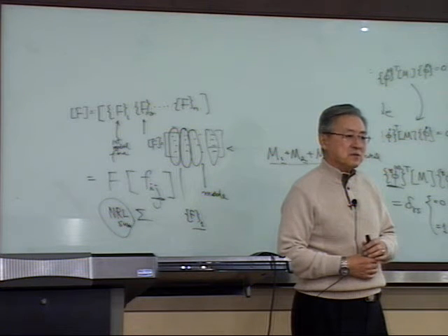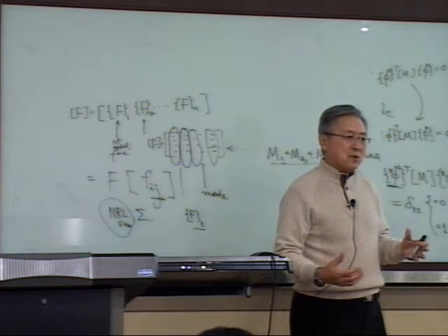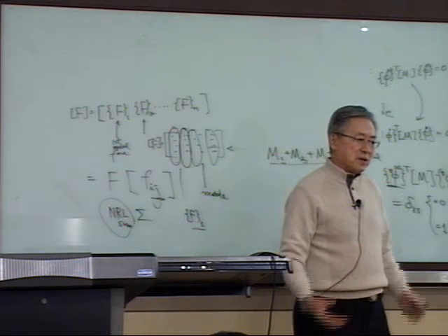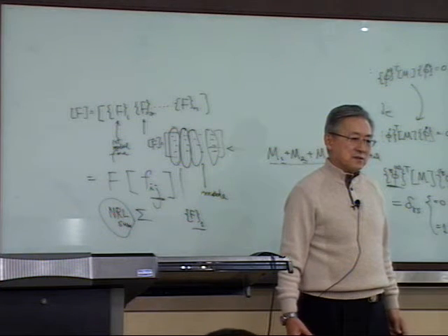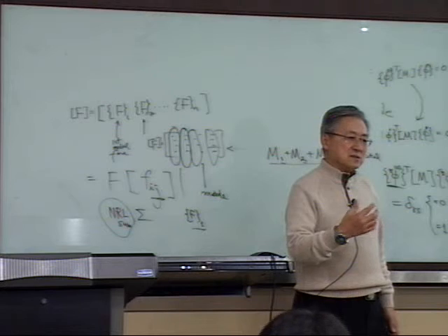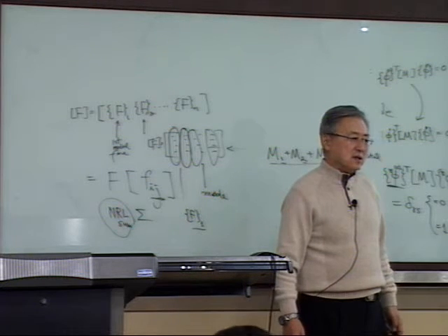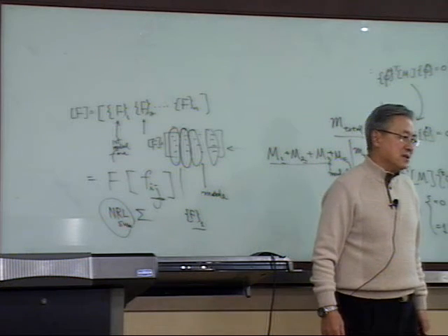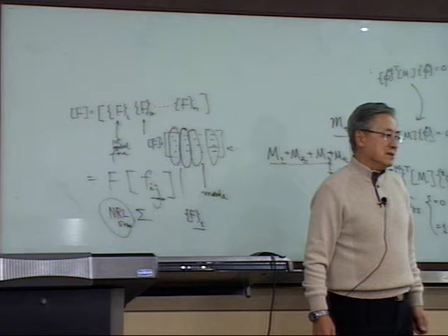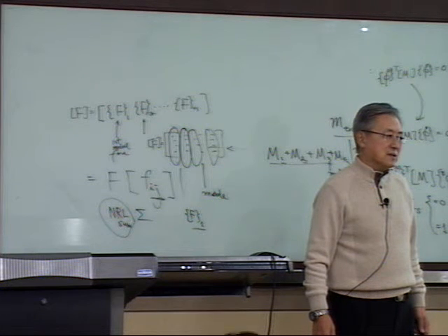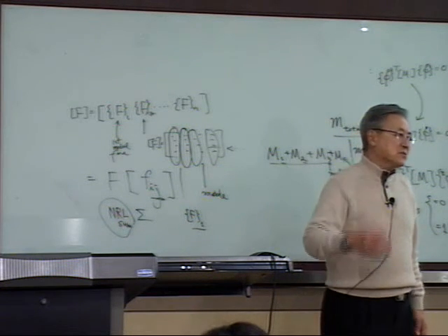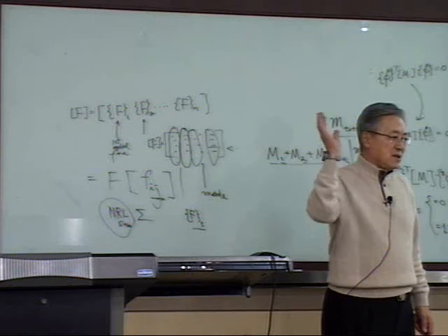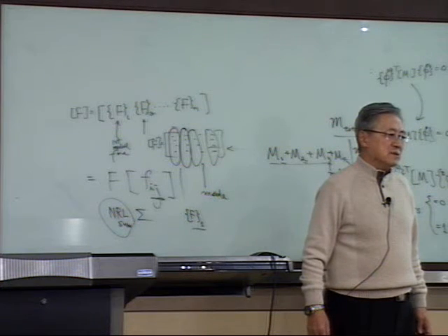Then believe it or not, lower mode has a tremendous contribution. Sometimes 80 and 90% is there already. Then a few additional modes, 80% criteria, done.